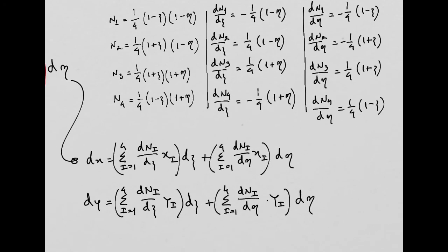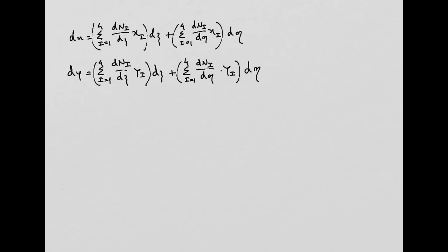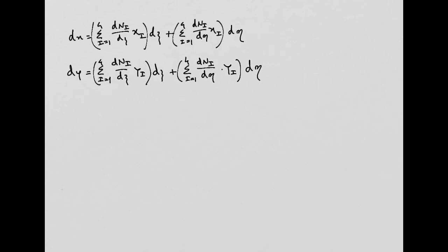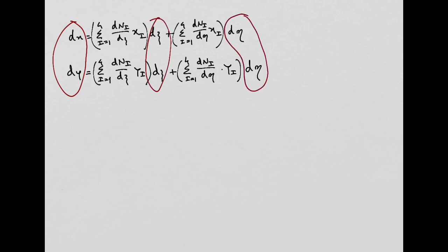So what I want now to show you, so let me paste this here, maybe shrink a little bit. So this important chain rule for the derivatives, if you look carefully, on the left hand side you have the physical coordinates or infinitesimal coordinates dx and dy, and on the right hand side you will have the natural coordinates d xi, d eta.